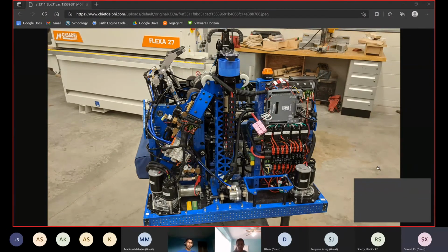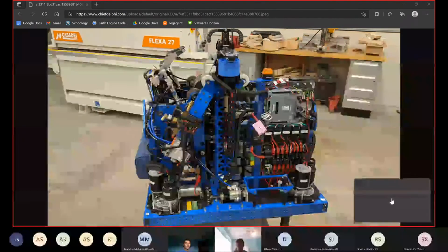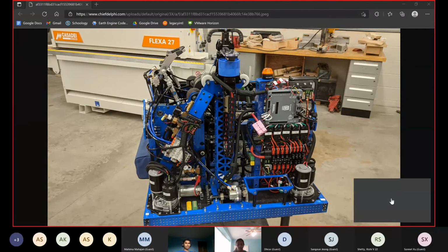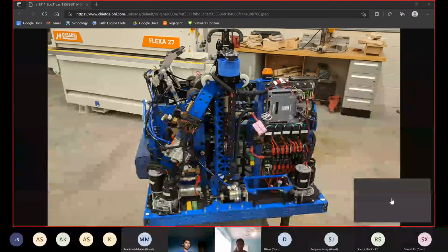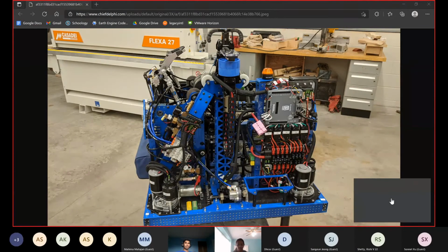That's why on the port you'll see reflective tape. Limelight comes in color. I remember when we were using it in the at-home challenges, it was all black and white, and then there's just a green circle for the inner loop. And we normally use reflective tape and base it off of that. Green light tends to reflect the best when compared with all other colors.